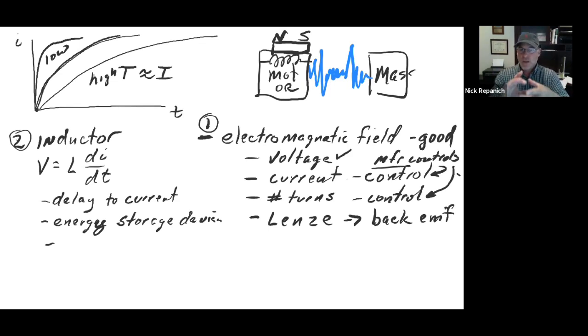You pick that one. You're not done just when you pick the size motor. That motor manufacturer is probably going to give you, in a stepper motor, 5 or 6 different windings to choose from. And that's what you're choosing: do you want high torque at low speed, which would be a high inductance motor, meaning they wound it a whole bunch of times, or did they wind it a lot less so that you have maintained more torque at the higher speed?